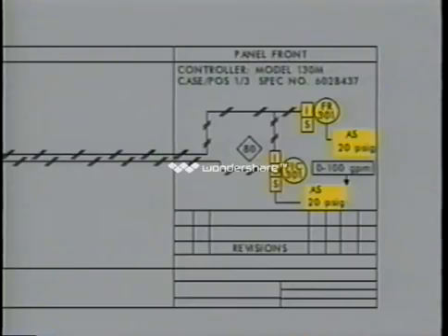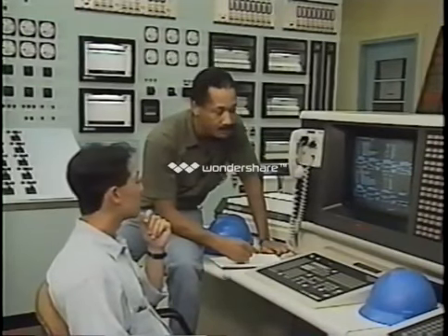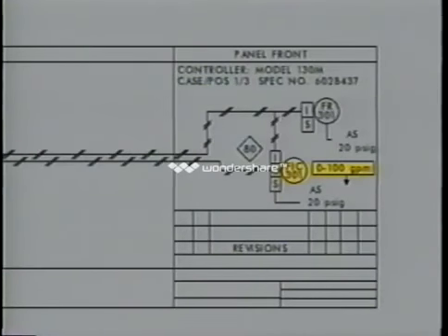Knowing the location and amount of supply air is important. You can tell which instruments have their own air supply source and use the information to isolate problems. The loop diagram also provides information about the operating range of the instruments in the loop. The information can be found inside a rectangle near the instrument to which it refers.